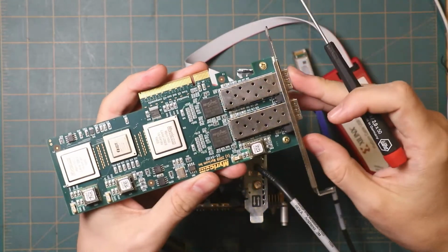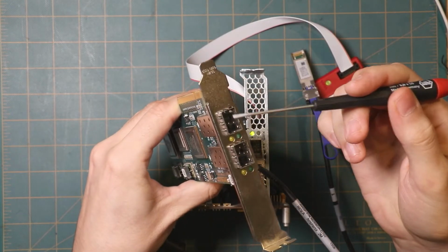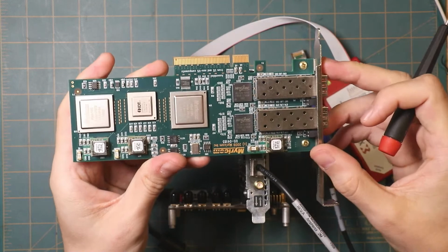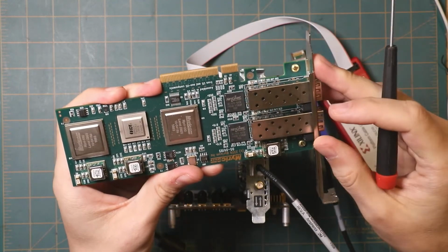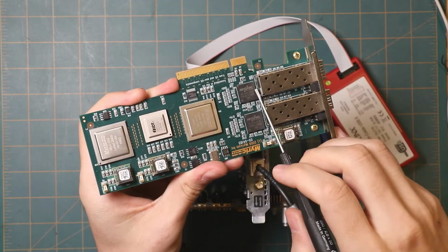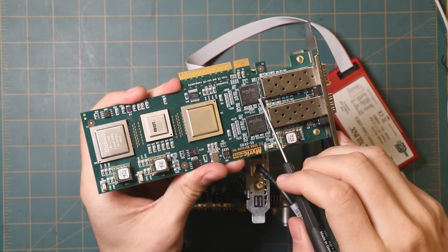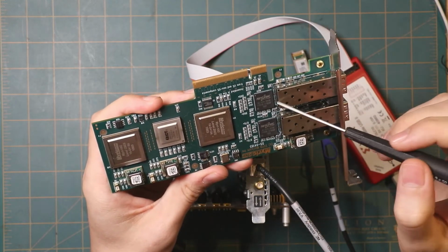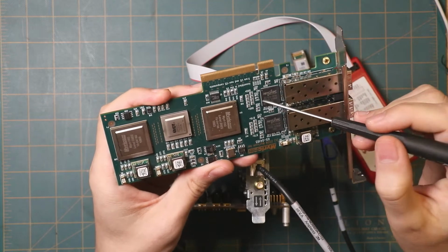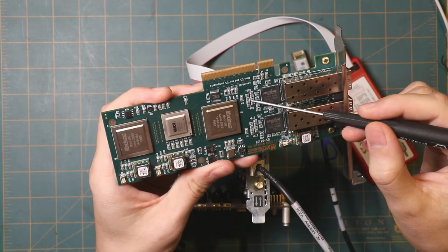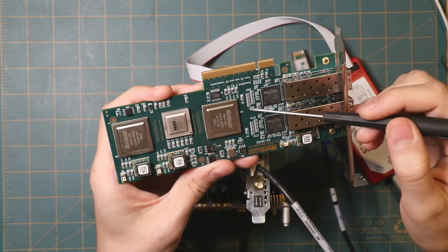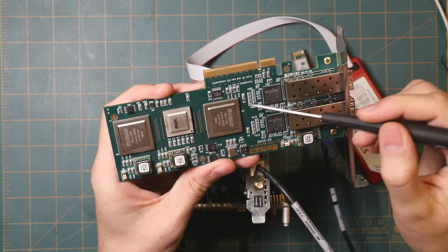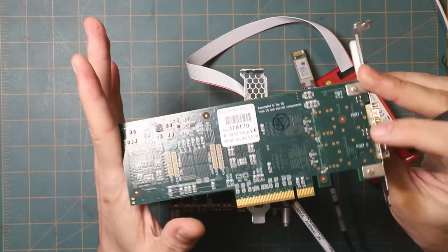It's the Ethernet side. So on this board, we have a pair of SFP+ interfaces, and they are connected directly to these NetLogic PHY chips. So these are the AEL1010 PHY chips. And if you look, you can see there's 2 little pairs of traces that connect the PHY chip to the SFP module. So those are going to be running at 10G, obviously. But on the other side, what's the interface? Well, we see 1, 2, 3, 4, 5, 6, 7, 8 pairs of capacitors. Well, that's for your XAUI link, right? We've got 4 pairs that are connecting these guys together.